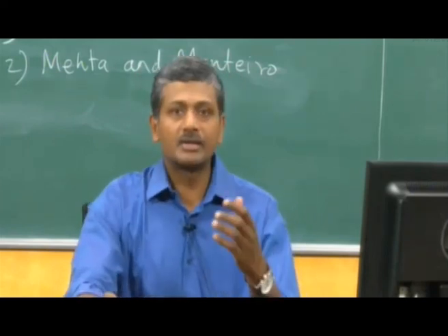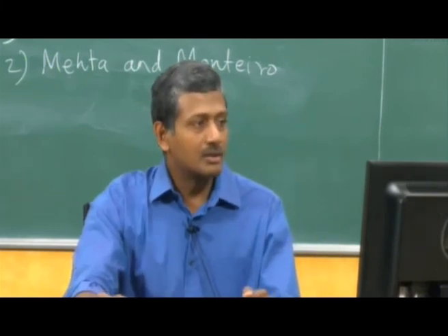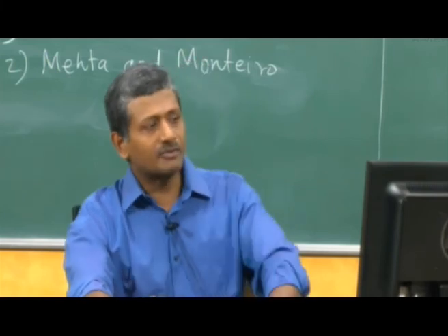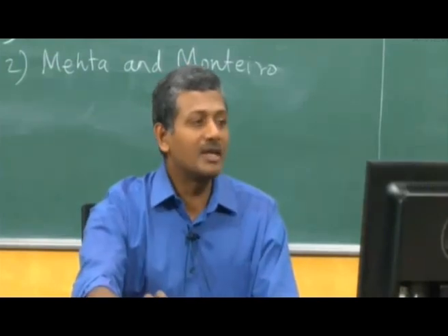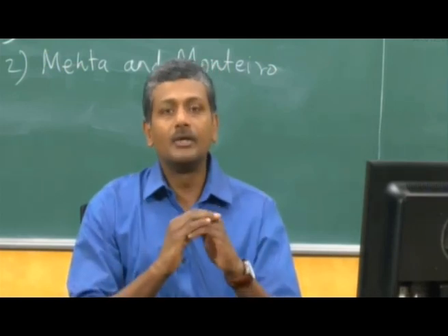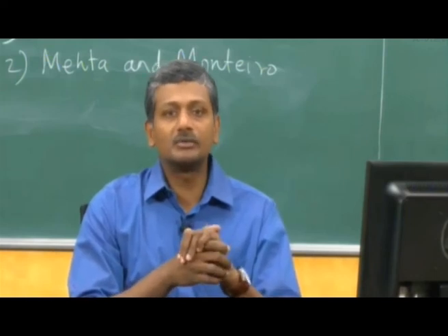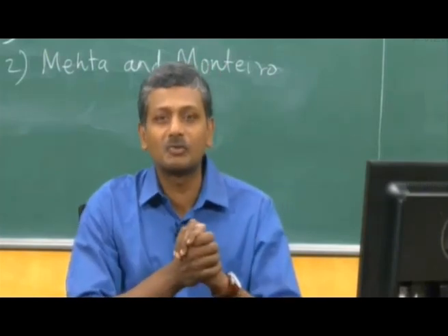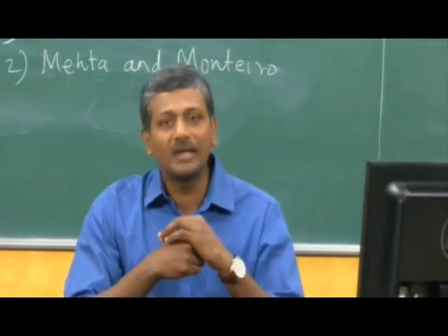I think I'll just round up today's discussion with answering a few of the remaining questions. One question is final setting time of cement after which concrete becomes useless. I'm not very sure what you're trying to say here. Truly speaking, after final setting time, the concrete has actually attained a given form, right? So you can't change that form after that final setting time has been achieved. So I don't think it's right to say concrete is becoming useless after that point. Really speaking, the concrete is becoming useful only after that point, because it is hardening and gaining strength and providing strength to your structure only after the final set.